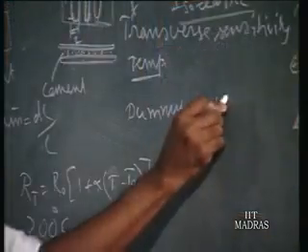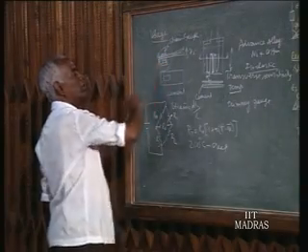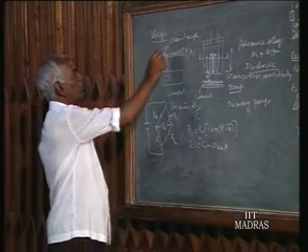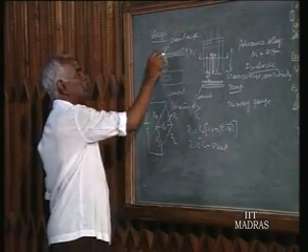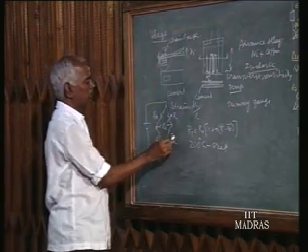This we have seen under bridge network. That is, we put another strain gauge fixed to the same base and don't load it and keep it in the same atmospheric conditions, and you will find whatever the temperature increase is there, that will produce similar effects on both of them, and similar effect put in adjacent arms.